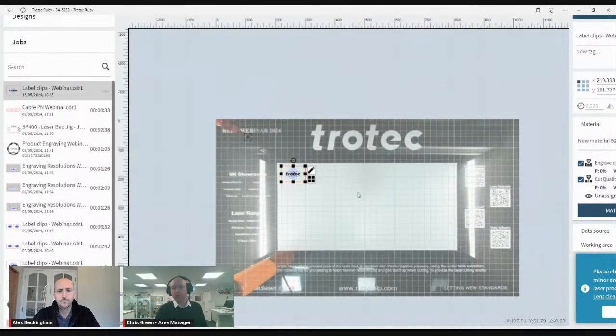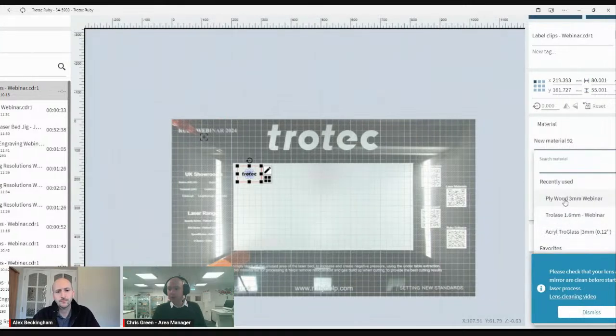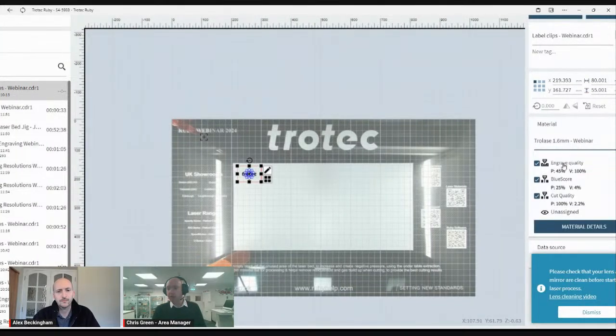Great for items such as, we'll show you in a bit, we have a very obscure item, but let's say a cut tree trunk for somebody that we wanted to engrave on, that's not a perfect circle, then we can align a text to that, and it just helps us out a little bit more. So here, like I said, I've got our diagram where we want it. We want to engrave, we want to score, and we want to cut. So I'll just choose my correct material. Again, we've got engrave, a blue, and a cut.